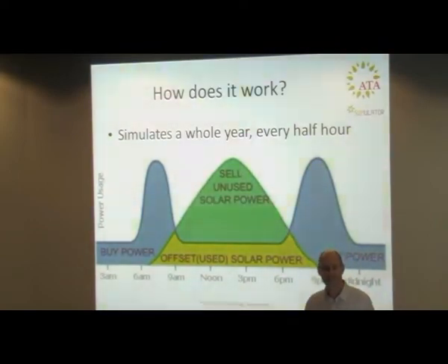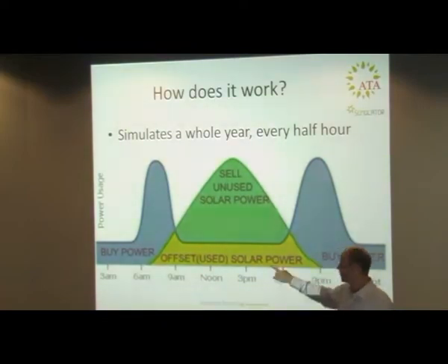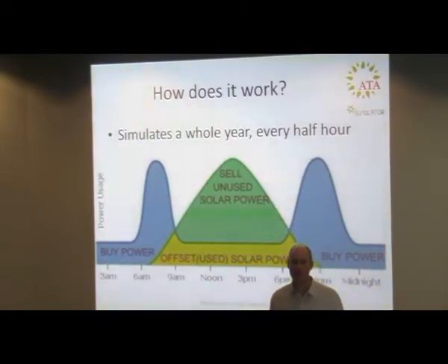Where did your demand profile come from? Oh yeah, the electricity consumption. That could be a winter profile, or a summer profile might be completely different. Right. Well, if you import your smart meter data, then it's based on your own data. That's the best way. Most of the electricity distributors in Victoria, there are 5 of them: Jemena, CitiPower, SP AusNet, Powercor, United Energy. Each of them has some way that you can get smart meter data. Most of them have a portal where you can log on to the internet and download the data.